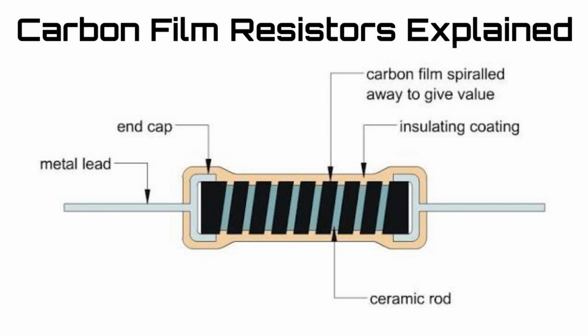These are just some of the many applications of resistors in electronic circuits. The specific choice of resistor type, value, and configuration depends on the requirements of the circuit and the desired performance characteristics. Resistors are versatile components that play a fundamental role in shaping the behavior of electronic systems. While carbon film resistors are a popular choice for many basic electronic applications due to their affordability, they may not be the best choice for high-precision circuits where tight tolerances, low noise, and low temperature coefficients are critical. In such cases, metal film, thin film, or foil resistors are often preferred.